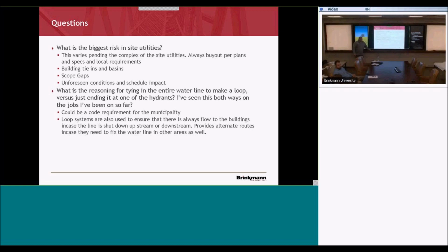I have one other one, kind of a Pfizer. When we did the Central West End project, we were talking about private versus public, and we had to come down an alley, so everything for the site water was private. We had 3 different fire hydrants. City of St. Louis wanted a backflow preventer before each fire hydrant, which Jacob had a picture of earlier. He said you can put that above grade if you're in a warm climate. Well, the City of St. Louis doesn't apply.